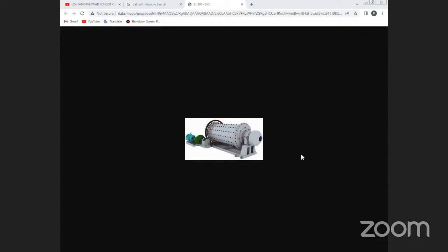The speed of the ball mill should be controlled. It should not move at a very high speed. At low speed, the balls slide or roll over each other, and a very small amount of the material undergoes size reduction. If we run the ball mill at a very high speed, then centrifugal force throws the balls towards the wall. This will result in no or less size reduction.